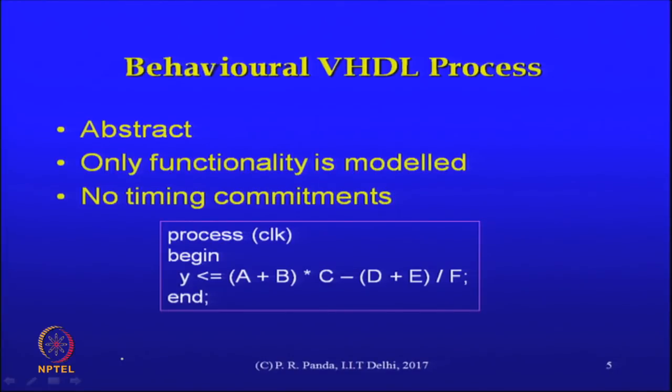Okay. So, let us define a VHDL process that is behavioral or high level, just for illustration. We are modeling essentially only the functionality here. So, you can see that this is sort of a complex expression. There is addition, there is multiplication, there is division. That entire expression is not going to be completed in one clock cycle obviously, but there is still some value, like we had argued earlier.